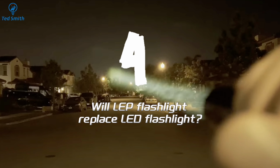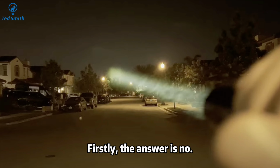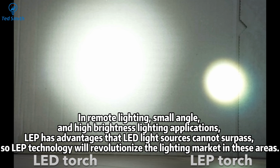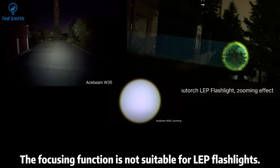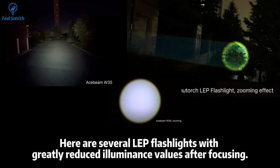Will LEP flashlight replace LED flashlight? Firstly, the answer is no. In remote lighting, small angle, and high brightness lighting applications, LEP has advantages that LED light sources cannot surpass, so LEP technology will revolutionize the lighting market in these areas. However, LEP light sources have obvious disadvantages in wide-angle lighting. The focusing function is not suitable for LEP flashlights. Here are several LEP flashlights with greatly reduced luminance values after focusing.